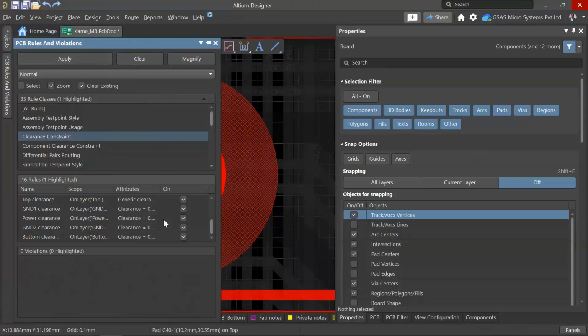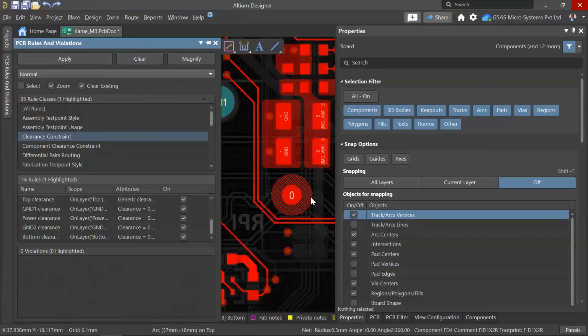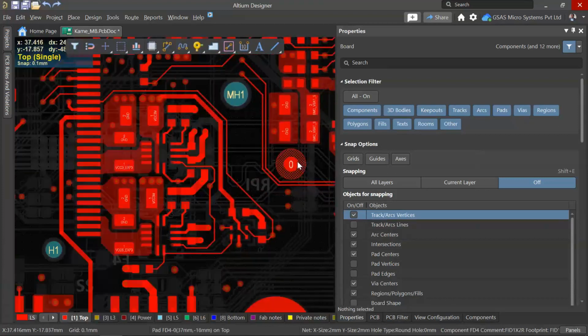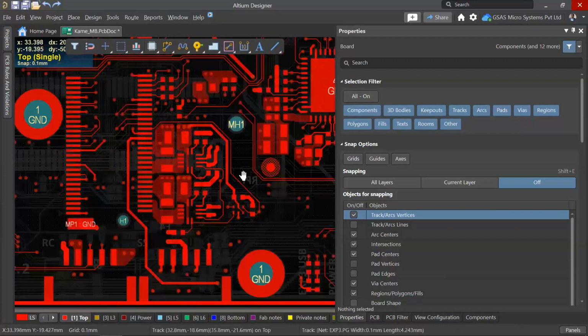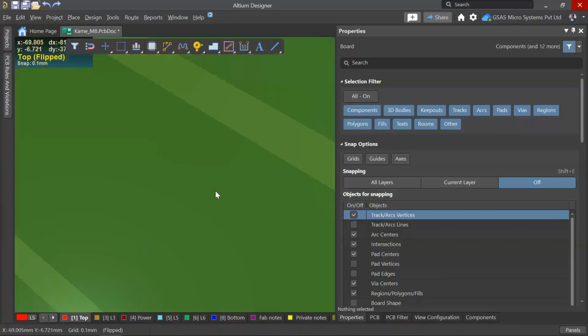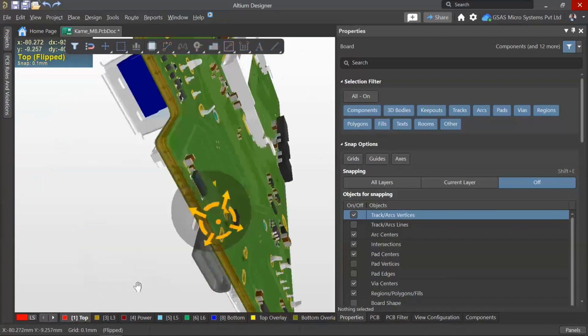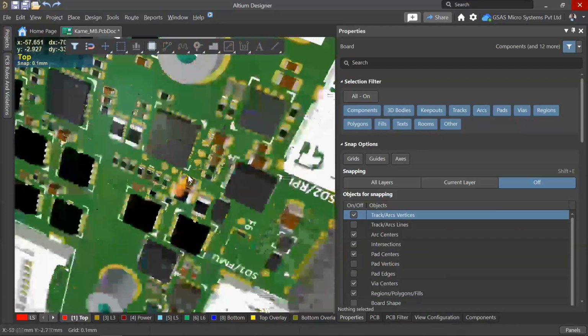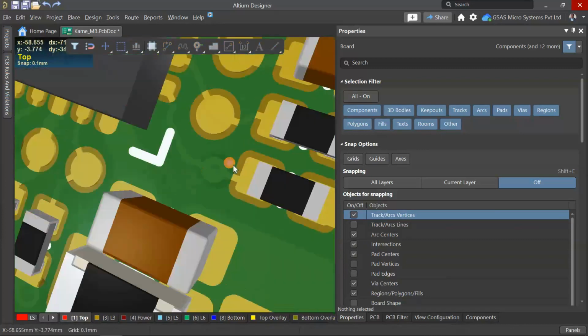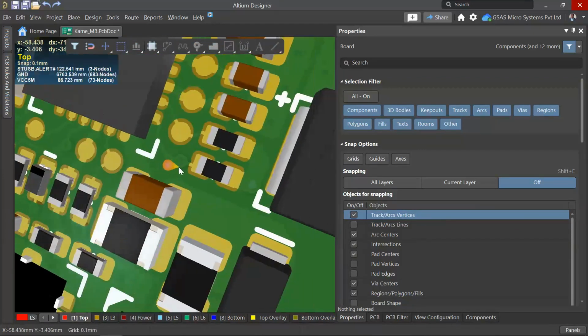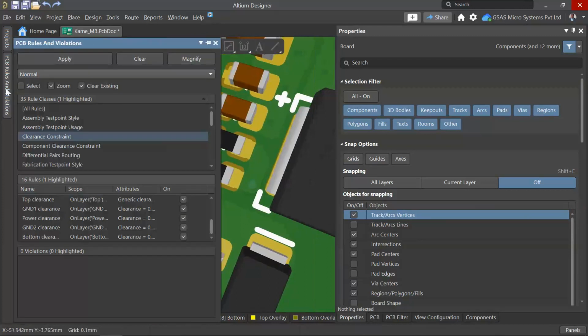The next rule we need to check, number 8, is the solder mask verification. That means the solder mask opening, the clearance between the components, what is the opening required for the component pad, and what is the opening clearance between the two pads. You are able to see this with the help of the design tools errors. Let us verify this.